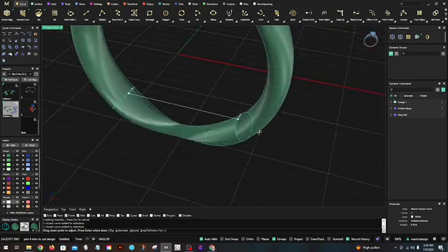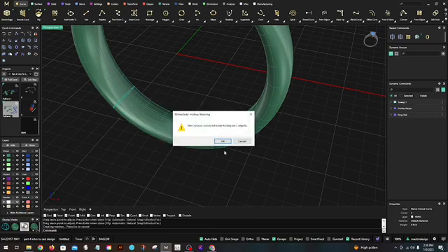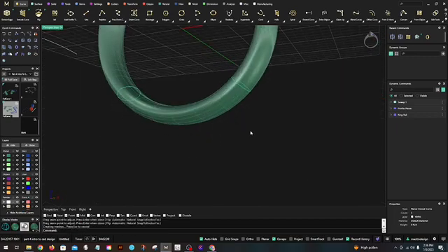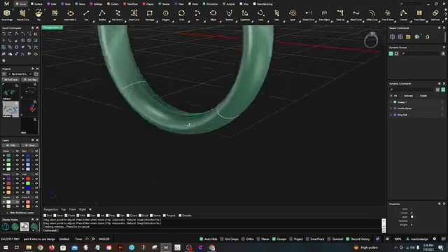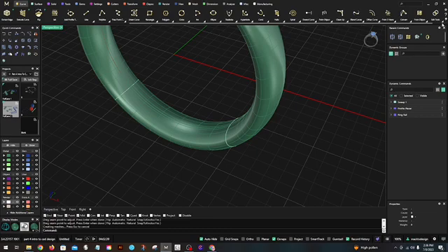It's on the finger rail and it's pointed out, so I don't have to adjust that. Now if I wanted to adjust it, I would just click here and it would point the other direction, or I could move this curve around, and if you hit your O snaps, it'll snap into place there. There we go. And now the seam or the sweep is smooth.